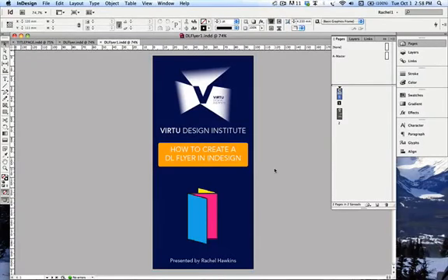There's just one more thing I need to cover before we bring this lecture to a close, and that is how to package your InDesign file for transporting it. So you're putting it on a USB, or taking it to a friend's computer to print it out elsewhere, and you're not quite finished. Placing images within an InDesign file is not the same as putting an image in a Word document. It does not automatically get embedded.